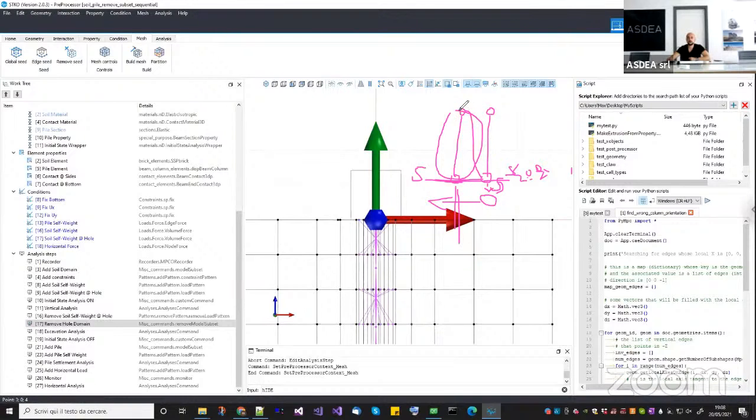So the trick here is to make the beam element a little bit larger in mesh size, so that, for example, you have something like this, in such a way that every node of the soil hits against a segment of the beam. This is quite annoying, and this is one of the reasons why we introduced a new contact element. I will repeat the same webinar as today, not the next one but probably the other one, using a new contact element that solves these problems, and it is also always convergent. So we will talk about this later on.